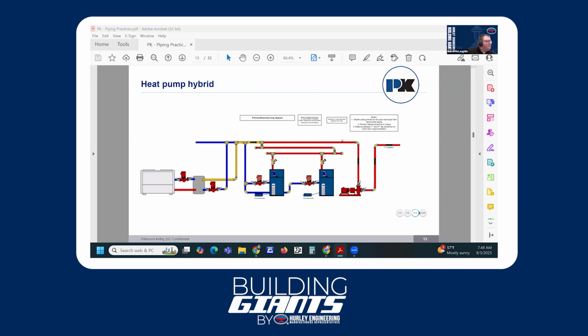But I wanted to point out here, like we had talked about earlier, if you'll look, the primary loop for the condensing boilers is actually plumbed in a reverse return scenario. So you can see our returns are coming back, and this one gets the first return in, but it's the last outlet, the last supply out to the manifold. That's done to try and self-balance these two and keep the flow equalized between the two.